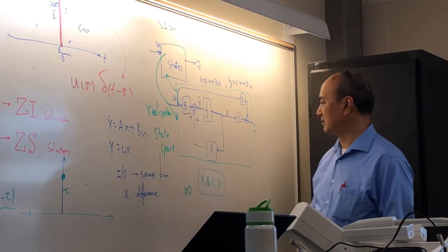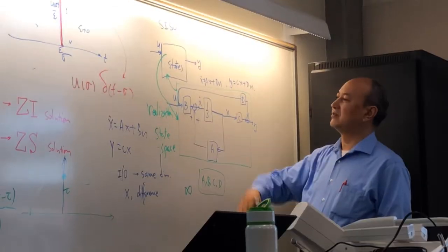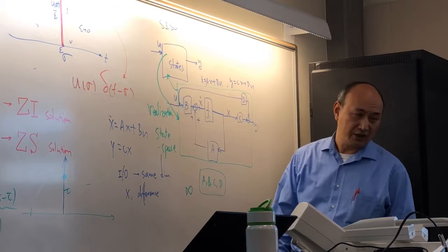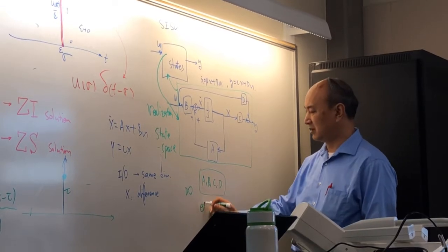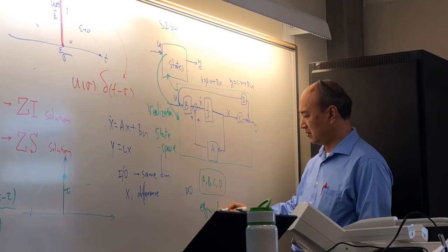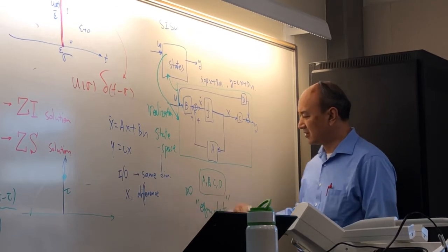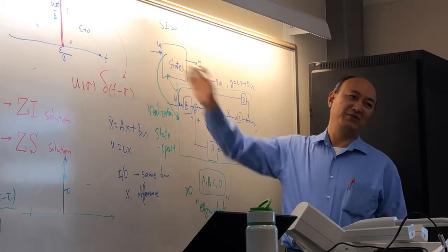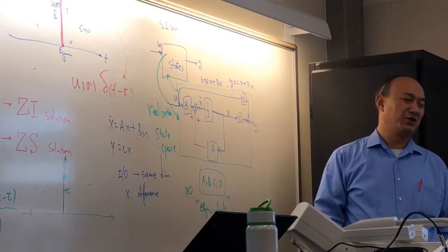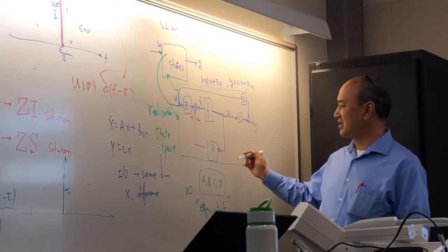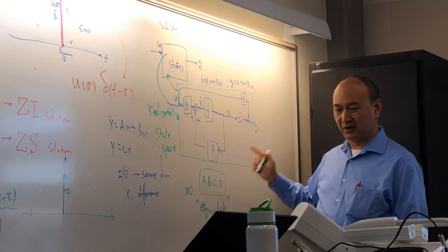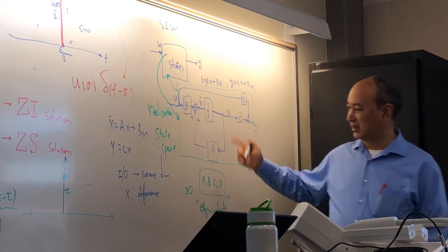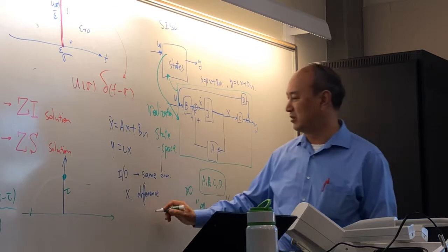Among many of the realizations, they are actually equivalent, in the sense that they are describing the same thing. So the internal representation using state space is never unique.